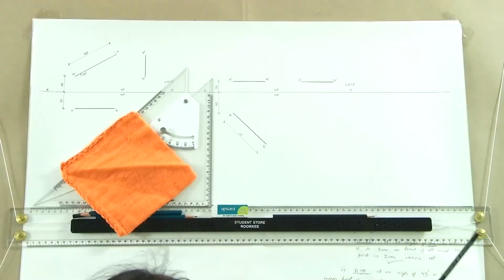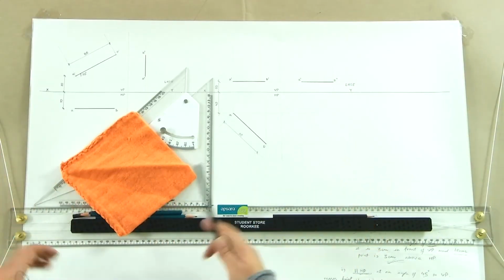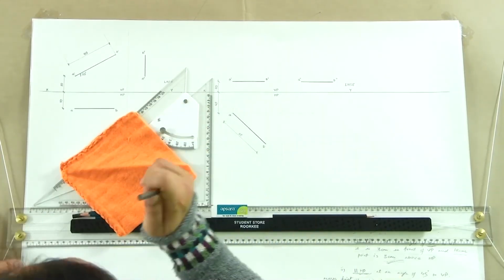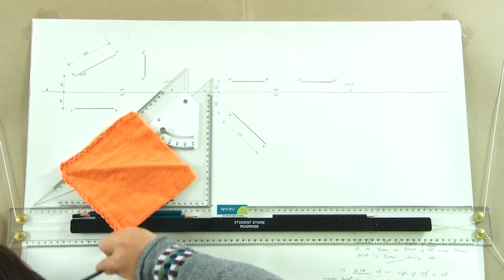To come up to this level where we can directly darken it, you have to have a lot of practice, and after practice, of course, it will be much faster, but until then draw it all in light and then gradually darken it. And the last thing that should be darkened on your sheet is the border. I am not making the borders here, but if you are to make the complete sheet for say submission in your class, you need to make a border, write everything, which should be the last thing that you do. Light border you could do, dark borders you should do later.